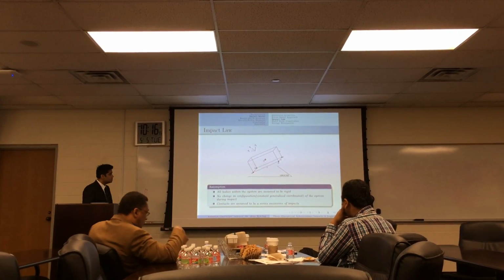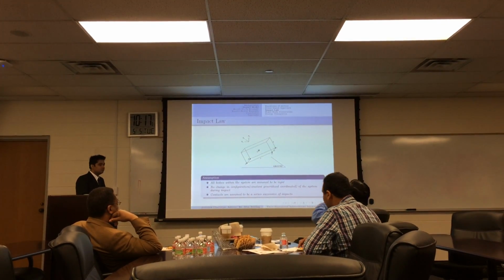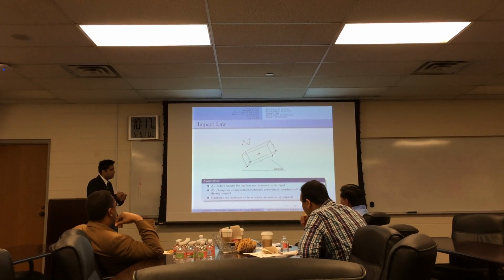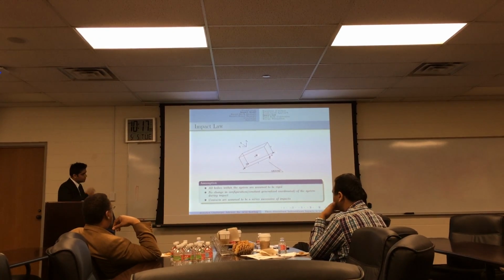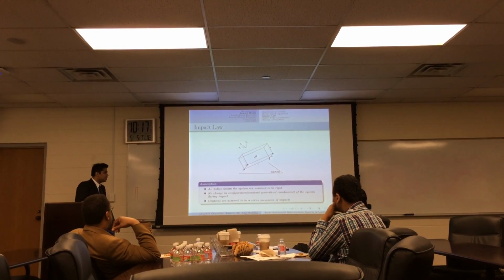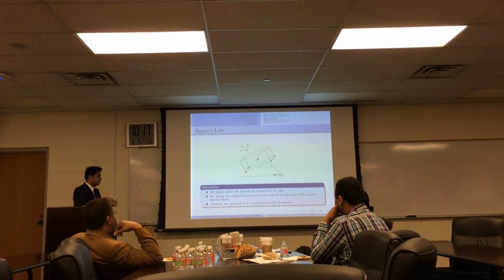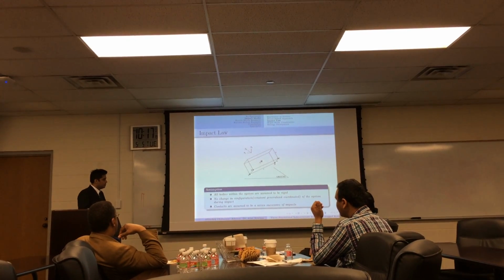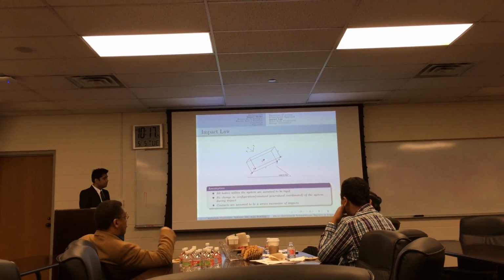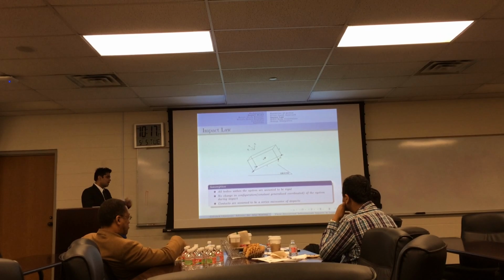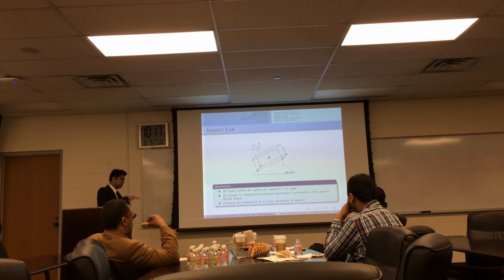So here are a few assumptions that we have made all through this work. All the bodies are assumed to be rigid, so there's no relative velocity or relative motion between different points on the body. And there's also no change in configuration during impact, which means the generalized coordinates during the impact would remain constant. Finally, contacts are assumed to be a series of impacts, and after a while it would be terminated based on the post-impact velocities.